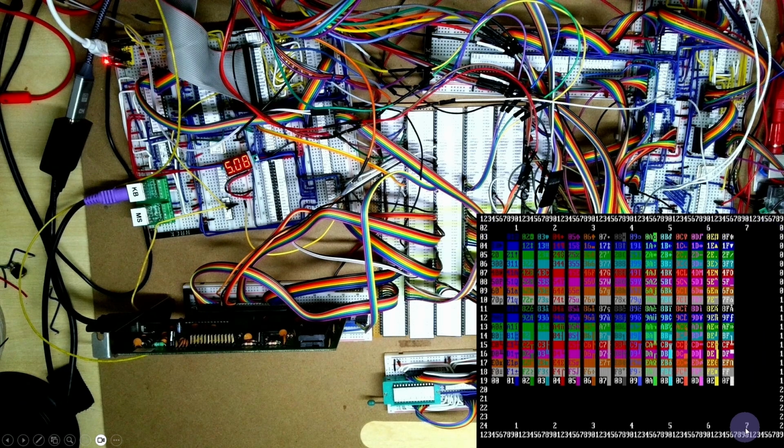But in order to get this working, we had to copy the video BIOS into main RAM and run the video BIOS from RAM. And then we just used one of the test programs we used previously to get this test pattern. So in this video, what we're going to try and do is to now get this working with the boot up process with the BIOS and see if we can actually run MS-DOS with the VGA card.